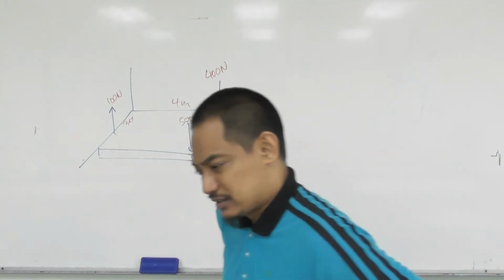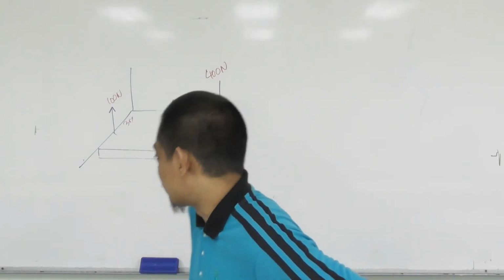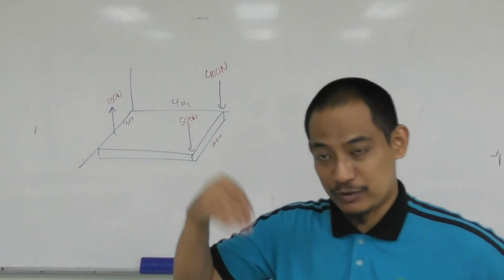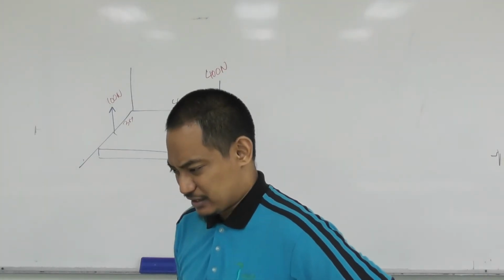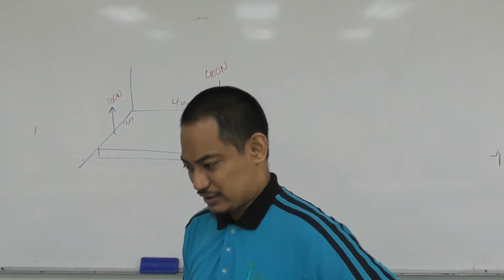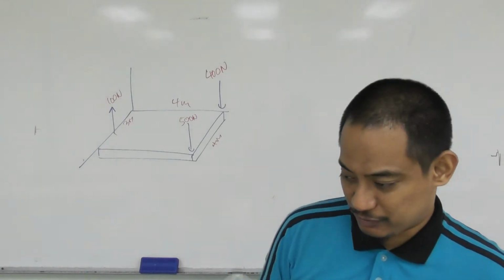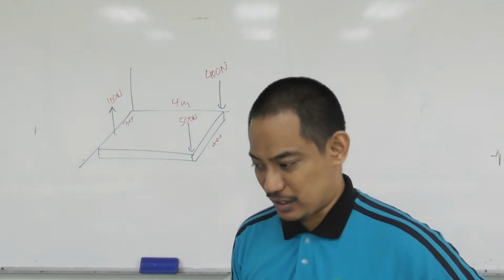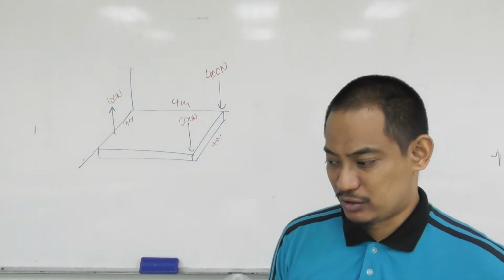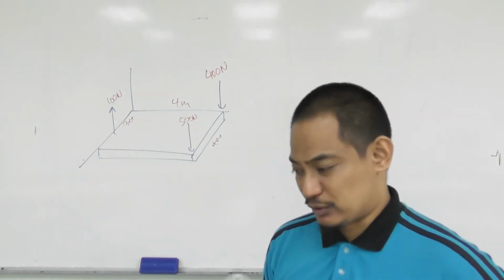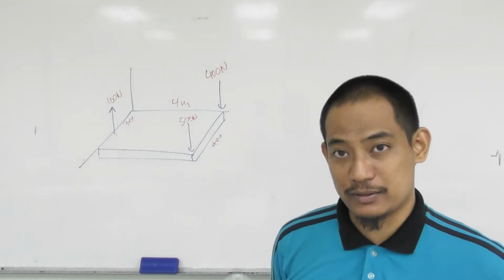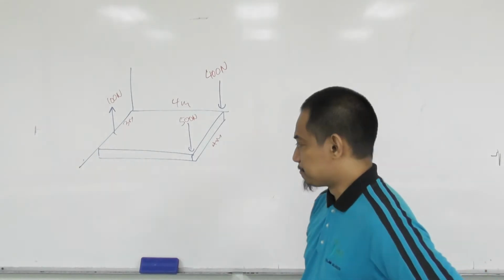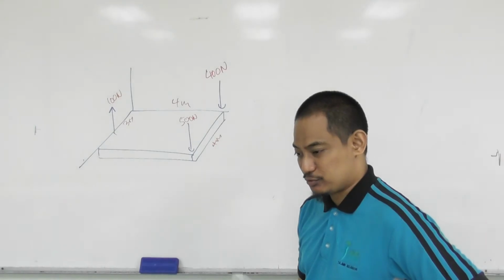The question says the slab is subjected to 3 parallel forces. So you have the forces, 3 parallel forces, all going vertical. Find the equivalent resultant force and couple moment at origin O. So that's the first part. Also find the location XY of single equivalent resultant force. So this question can actually be solved by vector or scalar, right? Which one should you first?